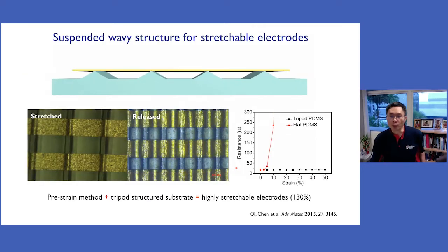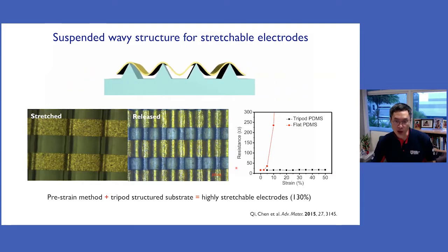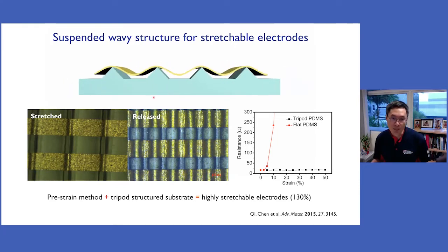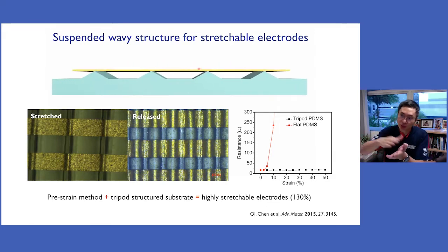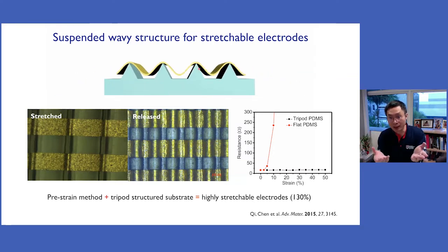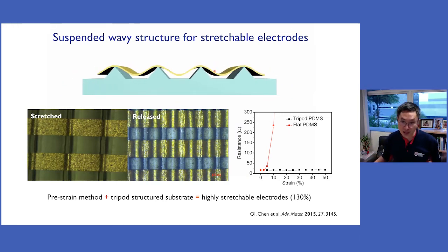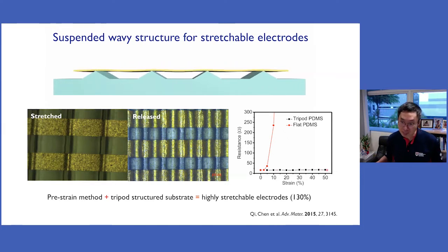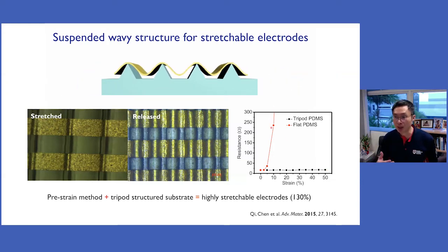So a few years ago, we also started to think about how we can really make stretchable and conformal electrodes. One of our first systems was to combine structured PDMS with gold ribbon. This gold ribbon was transferred to pre-strained PDMS. So when the PDMS is released, the metal will bend. And whether stretching or releasing, it still makes sure of good connectivity of the gold. So here, it can stretch up to 130% without changing the resistance. Typical gold, less than 10%, breaks already.